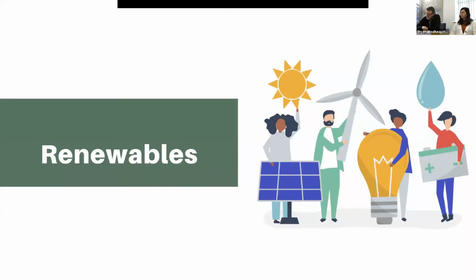Again, going back to what I said about the conversion factor, you have to remember that every unit of electricity that goes into it actually represents 2.08, or 1.95 as it is now, units of electricity to be generated. So it needs to be more than 2 just to break even. But at 4.5 and 5, it's well on that road.